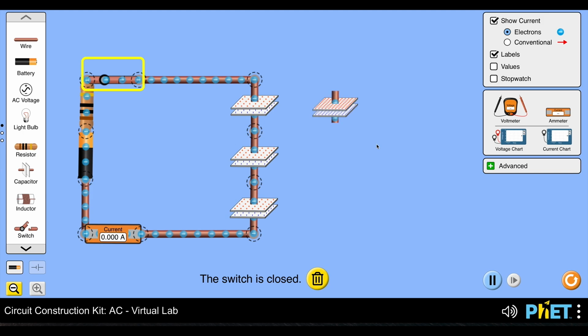On screen right now, you can see a screenshot of one of these identical capacitors from the parallel video, and you can see that the capacitor that was charged in a parallel configuration has a much larger concentration of charges on its positive and negative plates when compared with the capacitors here that were wired up in series. This is because the equivalent capacitance in the series case is much lower, meaning that I store less charge at the same battery voltage when compared with the case of parallel capacitors.